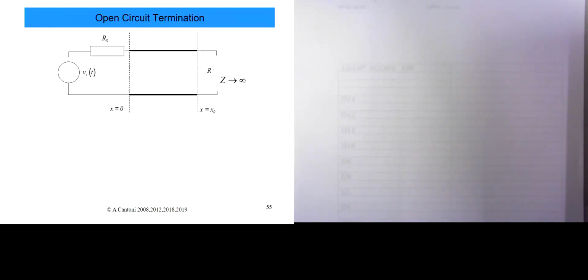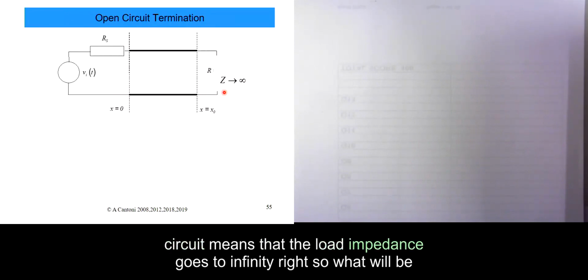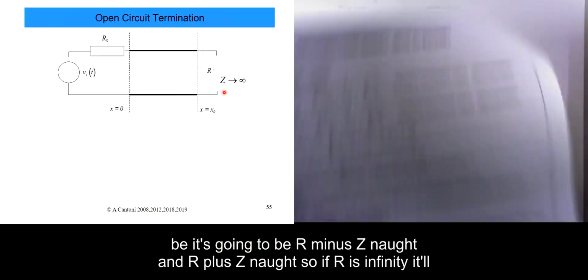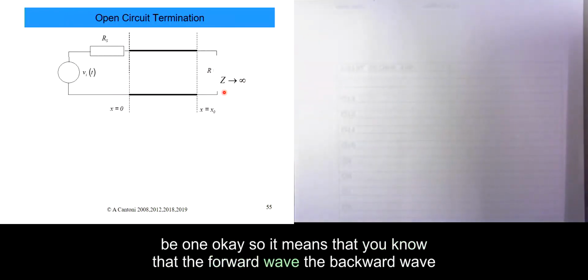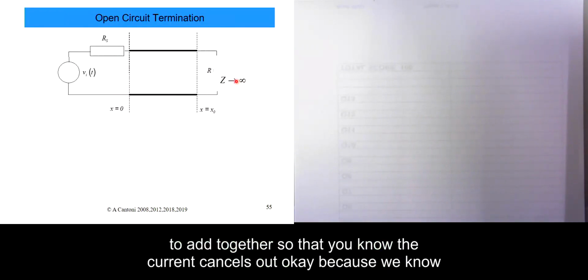One of those specials is the open circuit termination. Open circuit means that the load impedance goes to infinity. So what will be the reflection coefficient at an open circuit? It's going to be R minus Z naught over R plus Z naught. So if R is infinity, it will be 1. It means the backward wave is the same as the forward wave in voltage, because they have to add together so that the current cancels out.